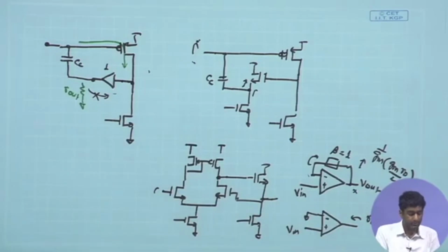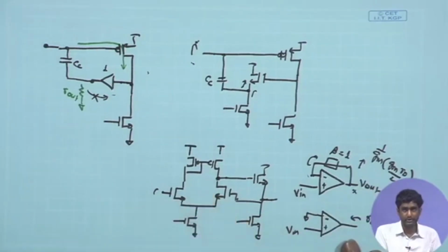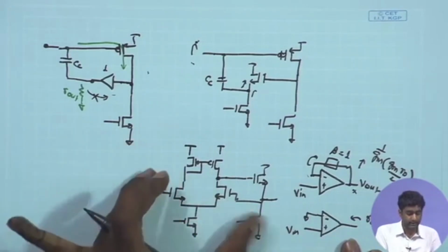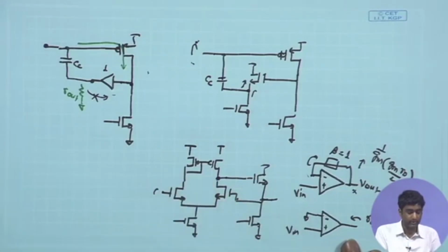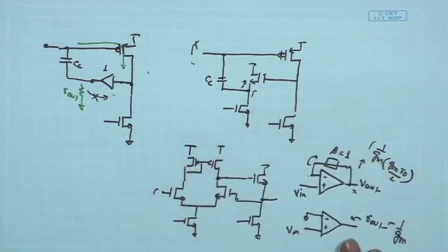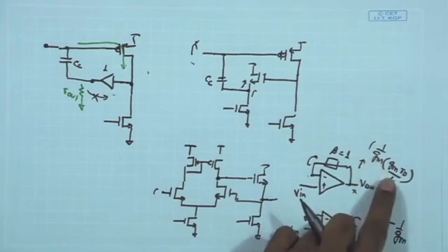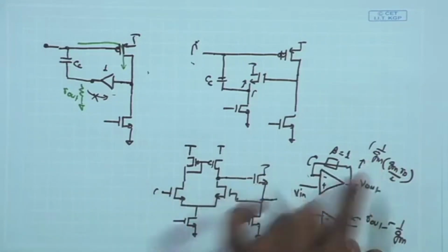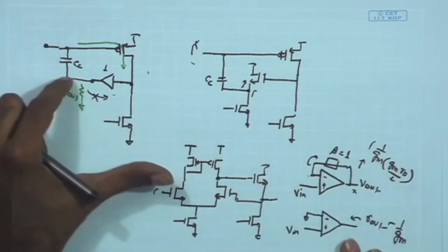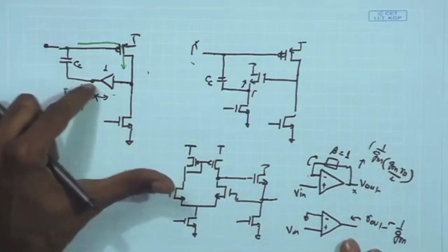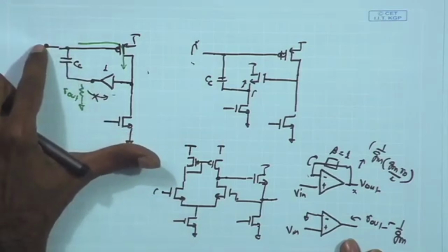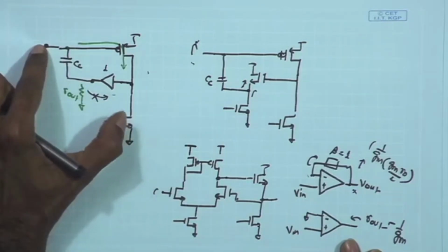And one of the good points over here is that we do not need a very precise feedback factor and hence a very high gain for this particular buffer. All we need is a sufficiently low output impedance, and for that we need to just have sufficient gain, so that the overall output impedance looking into the output terminal of this buffer is sufficiently lower as compared to the impedances provided by the output stages of our amplifier.